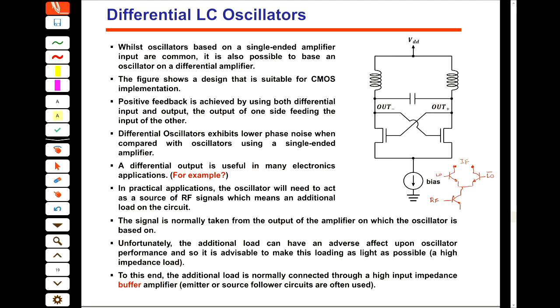So, in most of the mixers, single balanced or double balanced, no difference, we need a differential LO. So it's good to make a differential oscillator. So this is the application: the application of the differential oscillator is for the double balanced mixer.